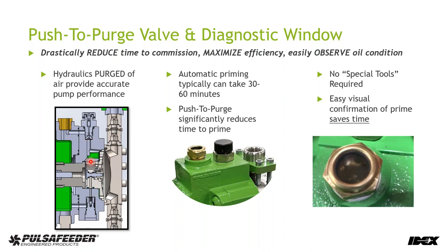So think of hydraulics as similar to your brake line, if you will. As you push on your brake pedal, you want to be able to get immediate response out of your brakes. And if you've ever experienced a squishy pedal, or you've got to pump your brake multiple times in order to get it to operate, it's because there's air in the line, or it's not solid hydraulics. So it's really important to purge the air from the hydraulic side of the pump, in order to make sure that on every stroke of the pump, this diaphragm is doing exactly what we want it to do.